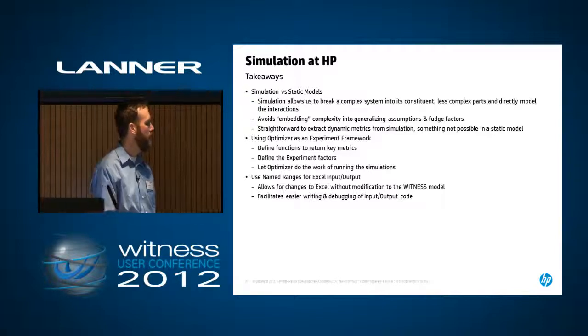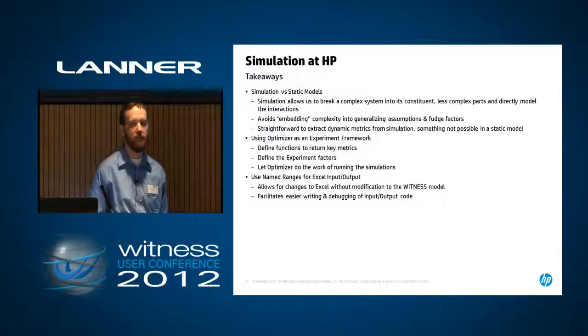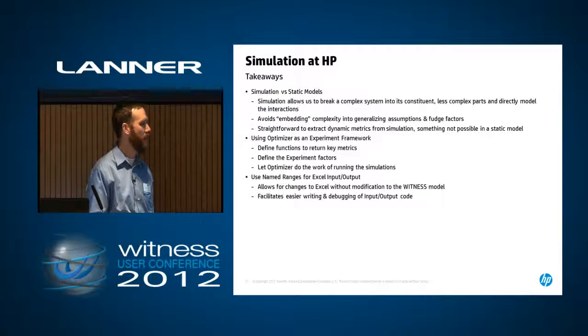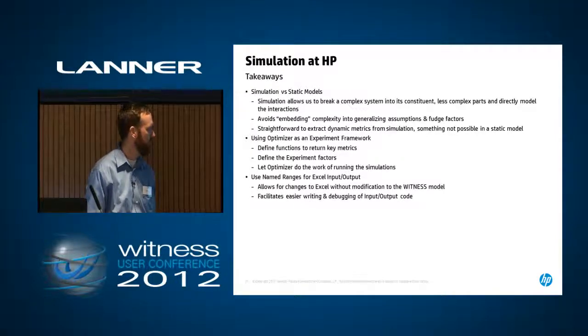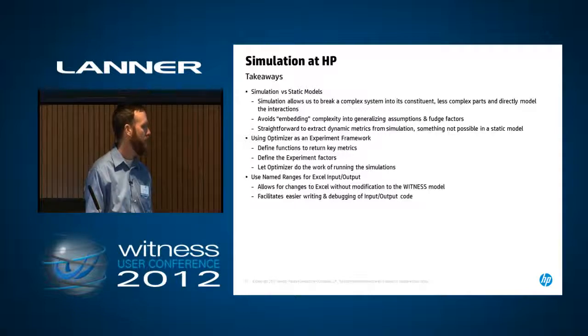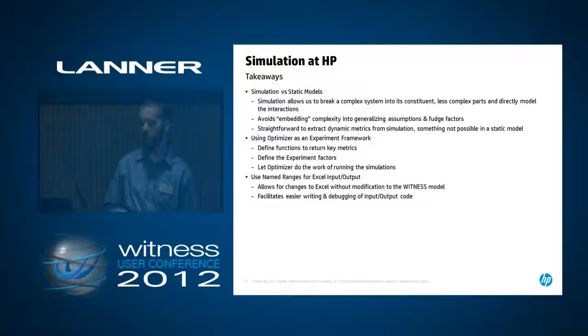And the third thing, very handy, is using named ranges. I mentioned this before, but it allows you to change Excel without modifying your Witness model or causing errors. And for me, it facilitates easier writing and debugging of the input-output code.